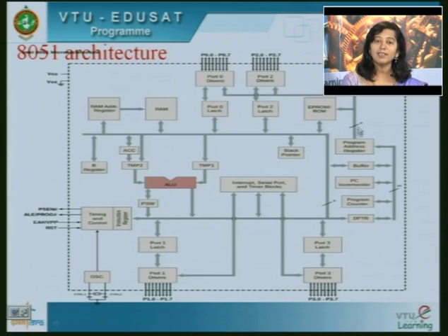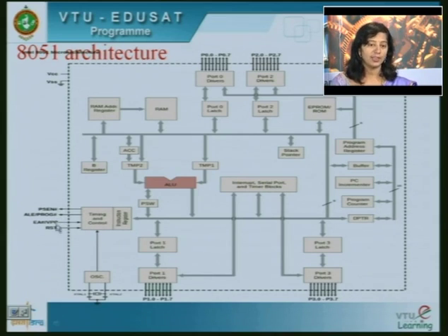So the address for where this program is stored is there in this program address register. Then you have a set of buffers, then the program counter and incrementing the program counter, and a data pointer to point to different data locations, timing and control block with multiple control signals connected here, the oscillator to which the crystal is connected.